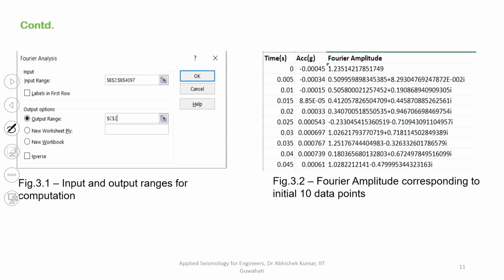One record of acceleration has been sensed by the sensor, which is available for the 1985 Chile earthquake mentioned over here. That means maximum up to 200 hertz, and correspondingly you can find out the Nyquist frequency, that is going to give you how much the highest frequency content available in your record, that is given as 100 hertz over here.